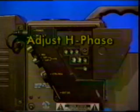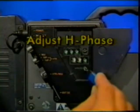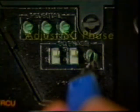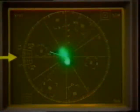Use the switcher to select one piece of equipment to be timed. In this instance, we'll use video camera number 1. Adjust the horizontal phase control on the input source, camera 1, so the sync pulse leading edge is at the reference position previously established, like this. Now, viewing the Vectorscope, adjust the SC phase of video source 1 to set the color burst at the 9 o'clock position.